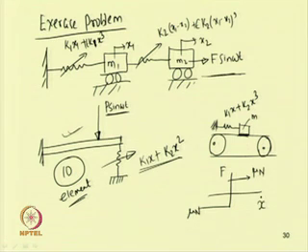So, at x dot equal to 0, or when x dot changes its sign, this changes from minus mu n to plus mu n. So, the system will have a cubic nonlinearity in the spring, and also a nonlinearity due to this damping. So, this damping force F(t) can be written as mu n signum x dot.